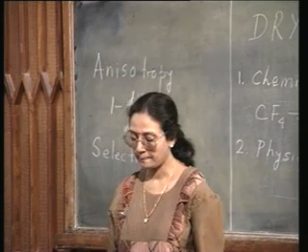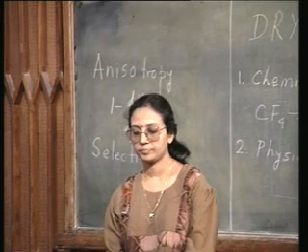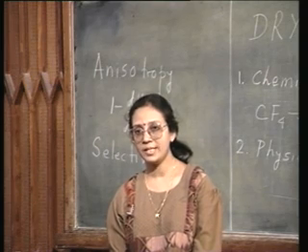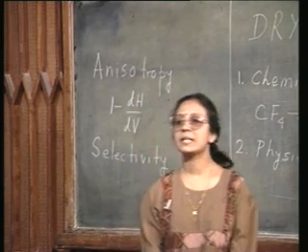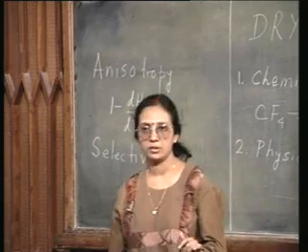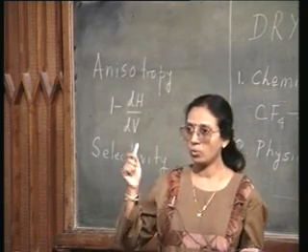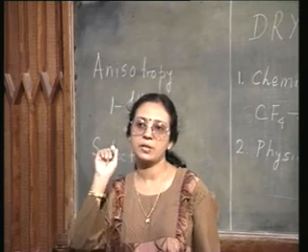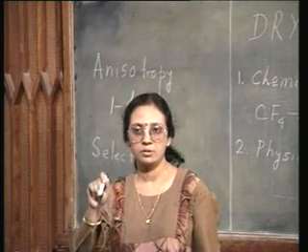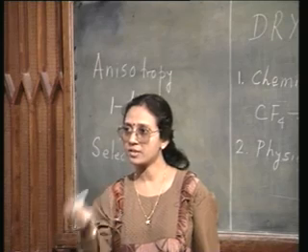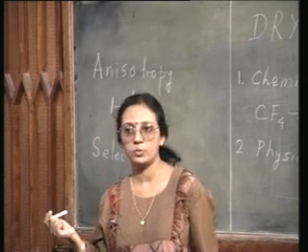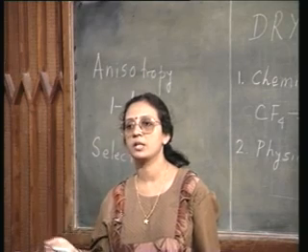You understand? So, here the selectivity is going to be the casualty, because whatever substrate you put in, high energy ions are going to be impinging on that surface and physically remove material. So, it is not going to distinguish that well between silicon and silicon dioxide or whatever.